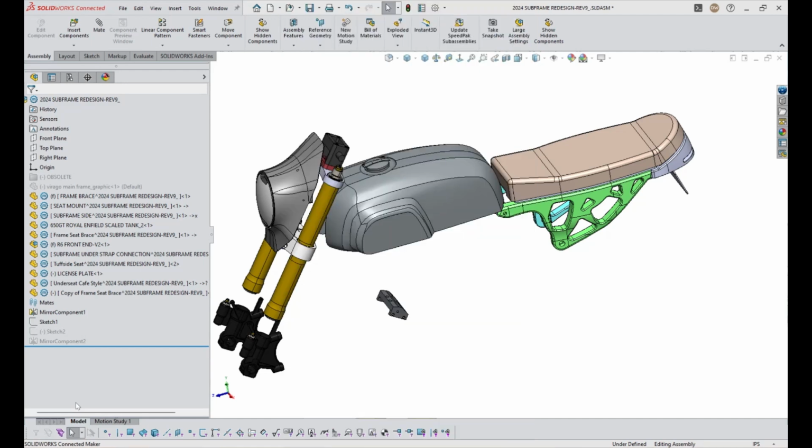This is day number 3 and today we're talking about virtual components. Virtual components are a great way to prototype parts within your design. I like to create a virtual component so that I don't change the external file. So a lot of times I might want to test out the design that I'm working on to see if it will work, and if not, then no harm, no foul. I didn't actually modify the actual external file.